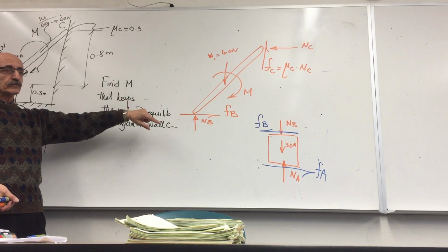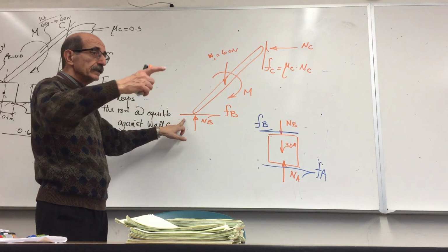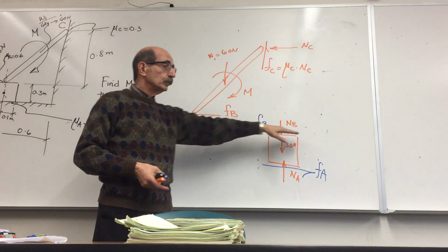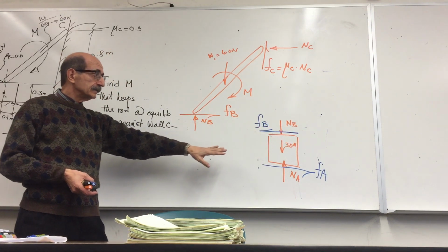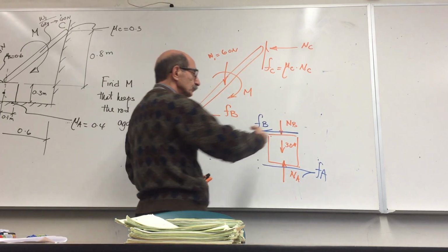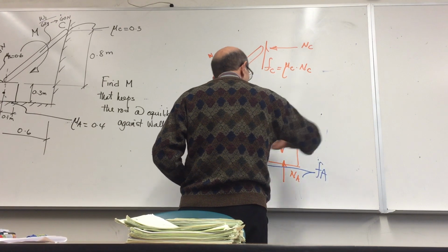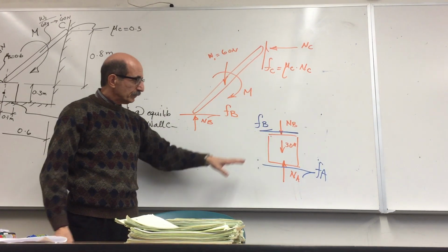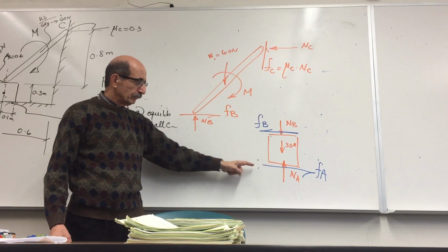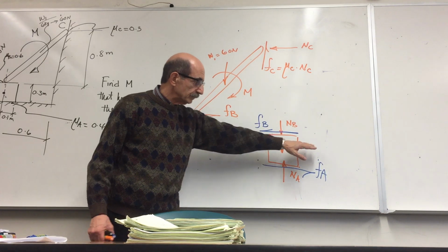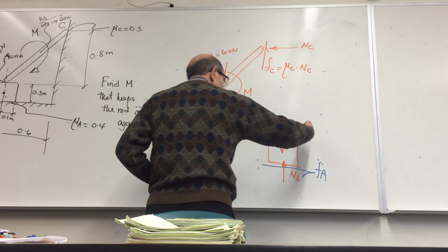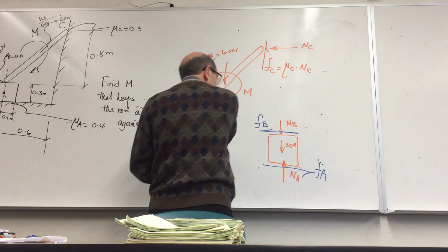So now using law of action and reaction, correspondingly, the force acting on the box, that same force FB, would be in this direction. And given that this is the force that is going to cause sliding or motion of this box, what is resisting that motion along this surface is a friction force in the opposite direction of the potential motion that this is causing, because the potential motion this is going to cause would be this direction.